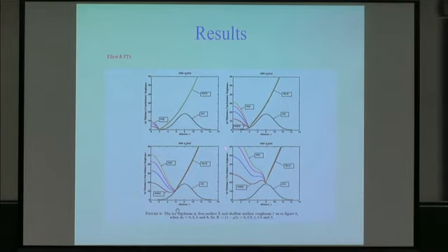So here we have the front, the spreading. There's the contact point which is moving eastwards, and as time goes on, the contact point moves up and over the roughness, and as it does so, it deposits ice behind it here. The amount it deposits depends on various parameters involved. But from this, we can build up a picture of a representative amount of icing that's deposited for a single droplet impact. What we then did was to extrapolate that hugely. So this is occurring over, say, 10 to the minus 5 seconds, typically.